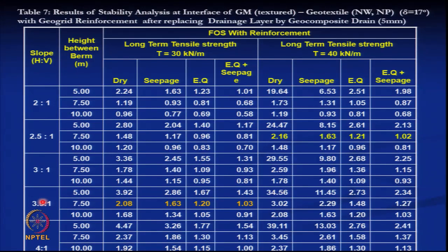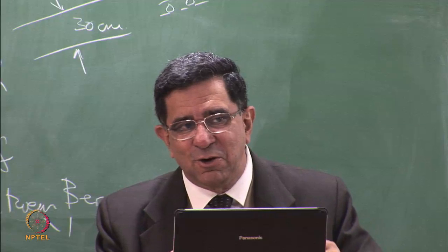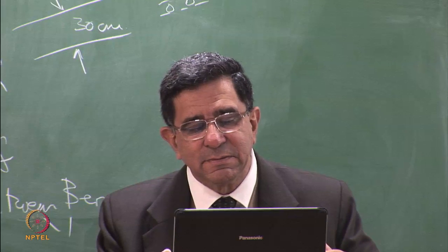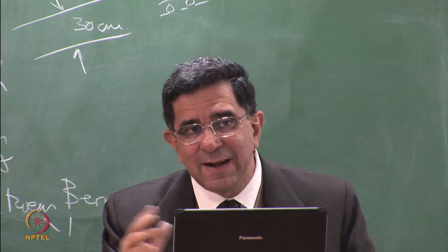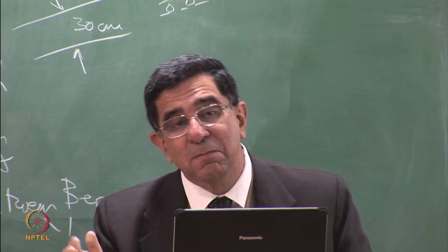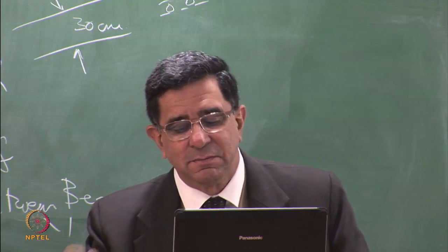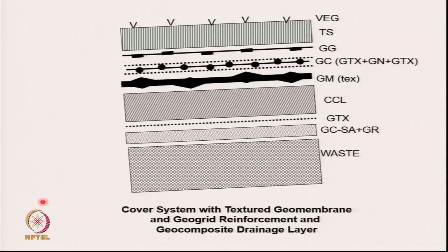I'm saying now, putting 30 kilonewton per meter, reducing it with a geocomposite, nothing great happened. Because 4:1, the delta would be very low, but beta would be much lower. So let me now go back and see. We have to, there are 1, 2, and 3 geosynthetics which are coming in rolls, right? And all of them have to be anchored at the top.